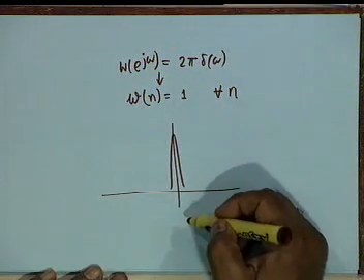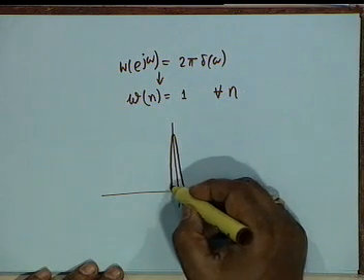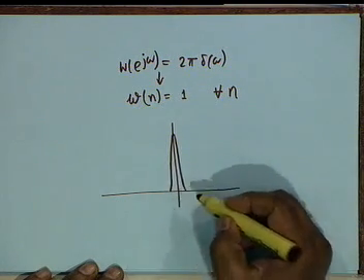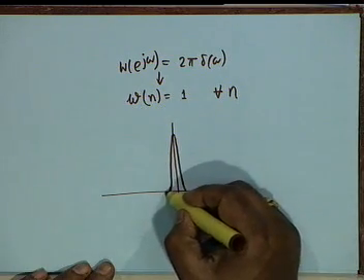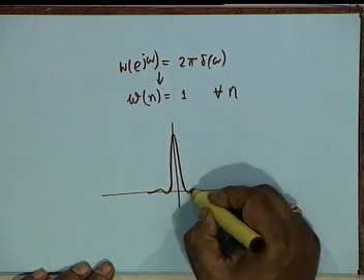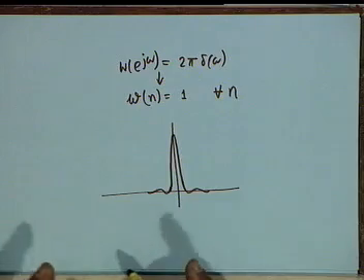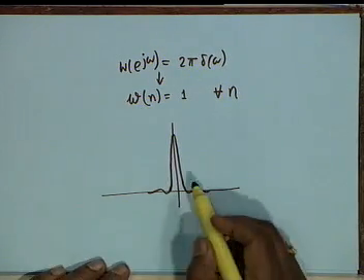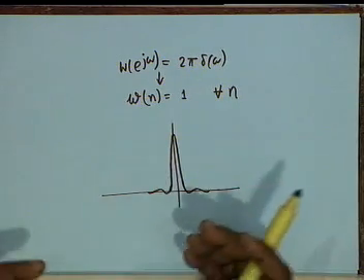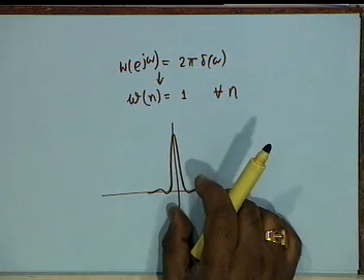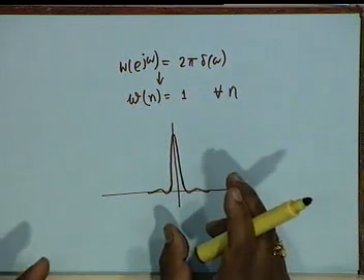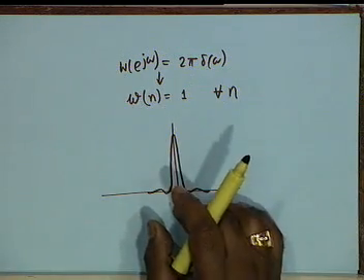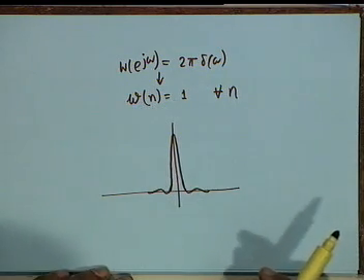It should be an approximation to an impulse function, and then all such approximations shall have side lobes, and therefore we shall have something like this. If we can get a window whose spectrum is like this, in fact the rectangular window has a spectrum like this, right? Except that we don't want it because there is a lot of Gibbs phenomenon. We want to smooth it out.